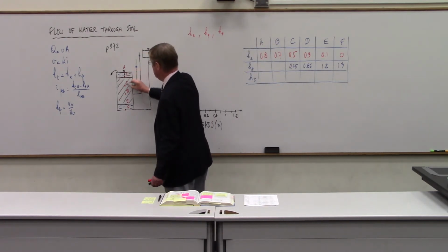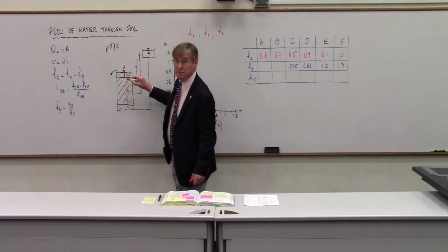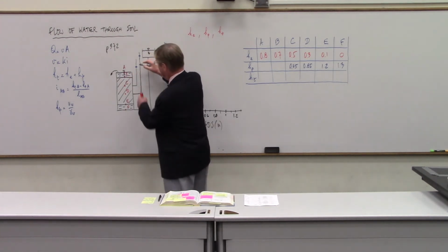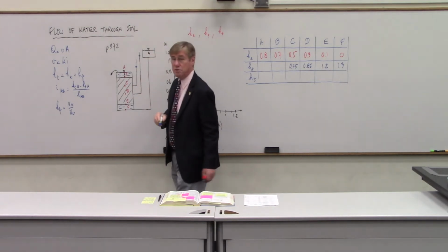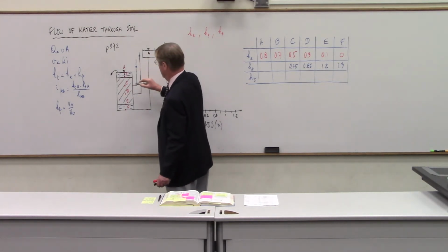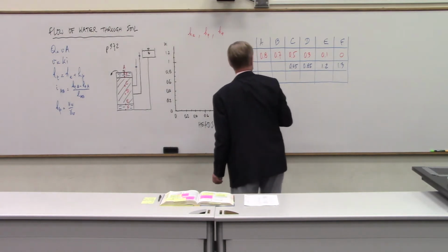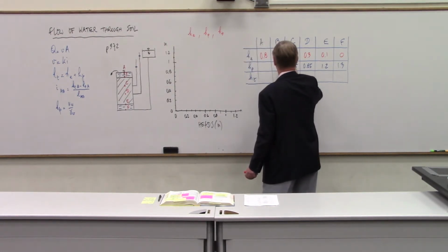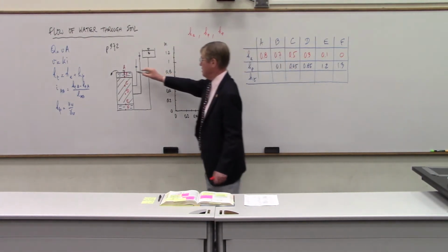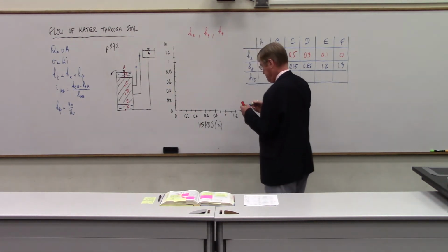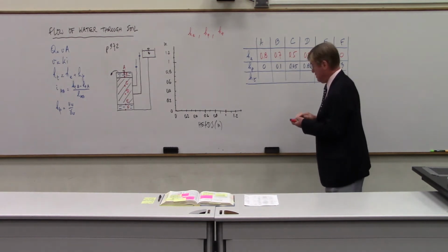Again, I couldn't go this way because I had to go through soil. So I was actually losing energy here, but here I've got a standpipe. I'm back to a static condition, if you wish. So then I just have the hydrostatic pressure. Then at B, now I'm through water only, and therefore the pressure head at B is just 0.1, the difference between A and B. And then at A, I've got 0. These are the pressure heads.